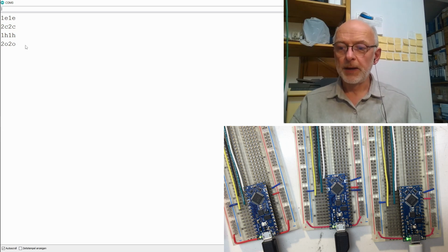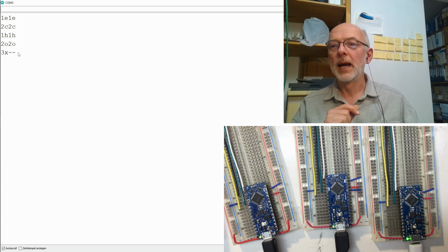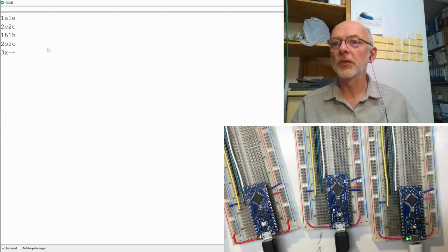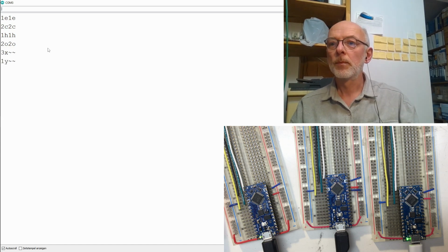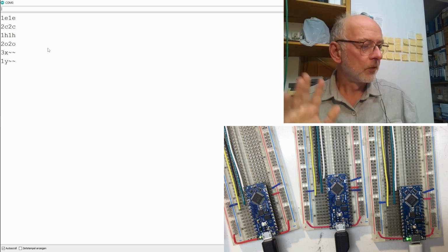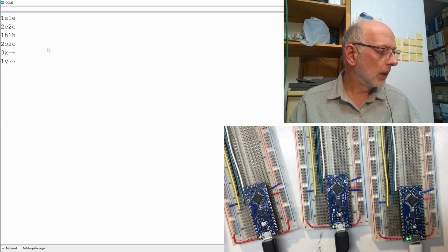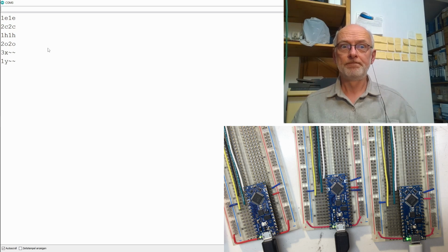But what happens if I now address with 3X a non-existing slave? Of course, we get a timeout. That mechanism is still working. And also if I switch off the first slave and say 1Y, no reply. Sorry, joking. But let's switch that slave on again and capture something on the oscilloscope.